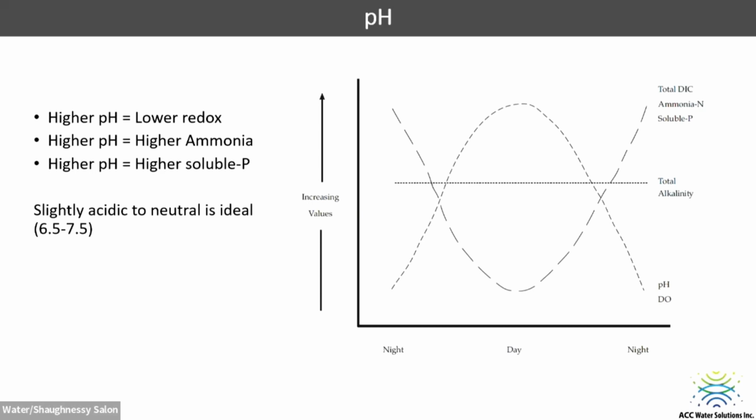A lot of the fish kills we see in lakes in Canada, they go, oh, we're having fish kills because we had a DO crash in our water body. Fish are really, really adaptive. They can find where the oxygen is in most water bodies. A lot of our fish kills in water bodies actually come because we spike the unionized ammonia levels because we get high algae blooms. So your pH goes up, your ammonia converts over, and that leads directly to a lot of the fish kills that we have.